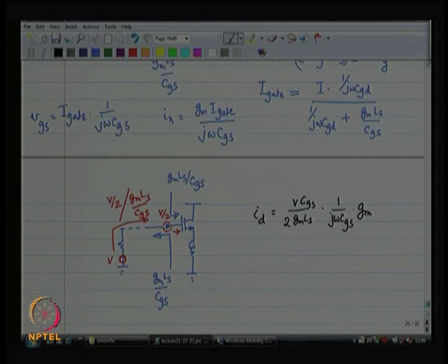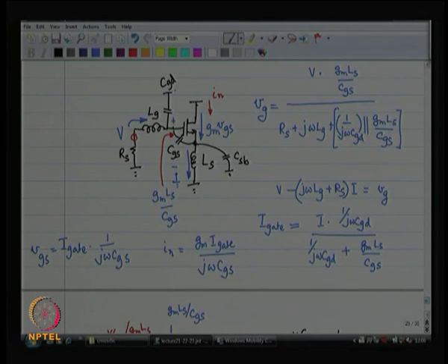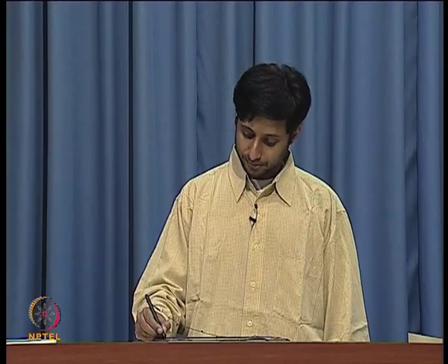Over here omega was there, we did not know what is the value of omega, omega could be anything. This is a very general analysis, you do not have to bother about the general analysis. Let us work at the particular frequency where the LNA is going to operate. The LNA is going to operate at the match frequency, and at the match frequency this is what is going to happen. The drain current is going to be so much times the Thevenin equivalent of the voltage.